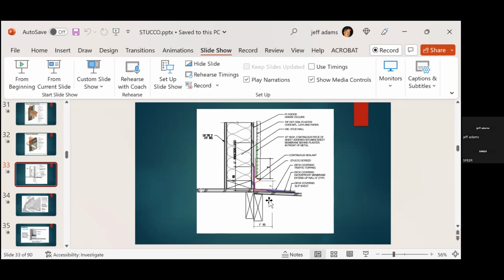It goes into detail that this drip edge portion here is not allowed to be sealed, and it's being sealed by elastomeric polymer paints, even latex paints, that all has to have a razor knife, and it all has to be cut and scraped off there so the water can get out of there and drip it. All your flashing details, your kick out flashings or turnout flashings at the roof line, all of those are being completely sealed shut with these products, and the water's not getting out of here. Okay, so it is important to keep those cleaned out.